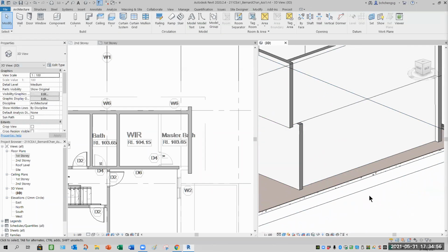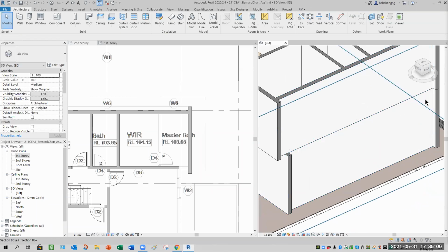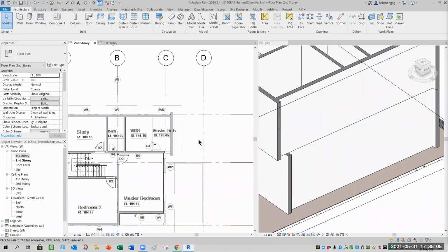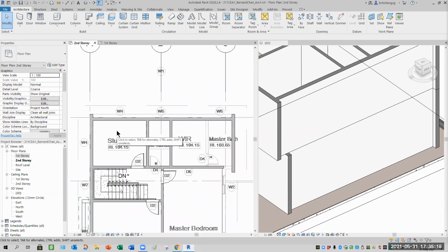Subsequently, here, you should have a wall connected. All right, for this piece. So how you going to connect them? You see or not? See, there's a latch. So that means here it should be just a normal 200 mm thick slab or pure concrete. So you got this as a ledge. All right.